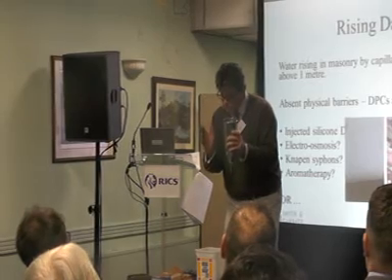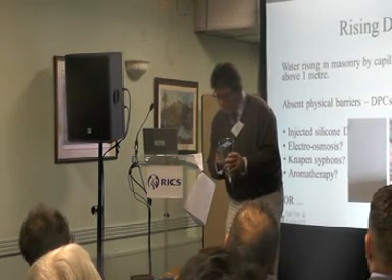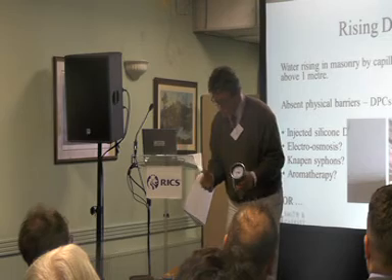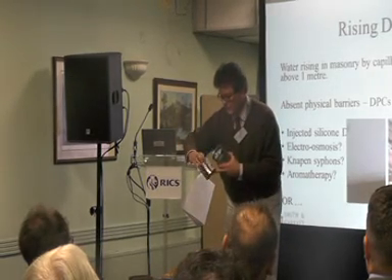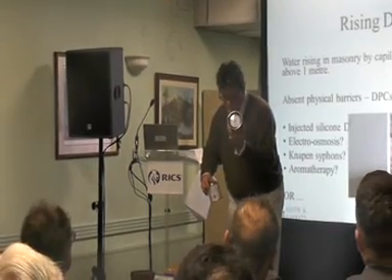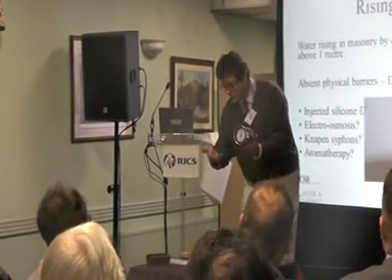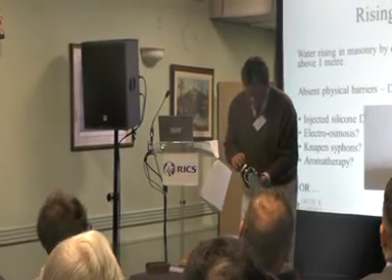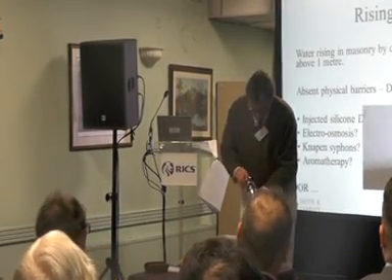I think probably we'll stop dealing with the metering now, but anyone who wants to see the speedy and know how it measures: you put in calcium carbide with a known measure of stuff you've drilled out of a wall. You drill it onto tin foil so that you don't touch it. You put it in this chamber. You mix it with a bit of carbide with the lid on.